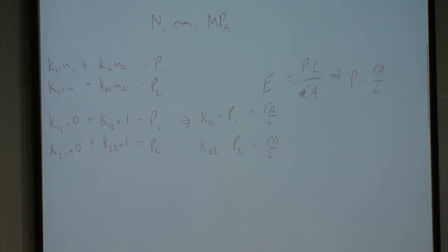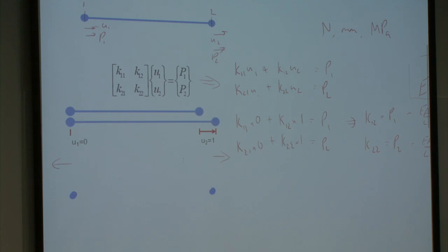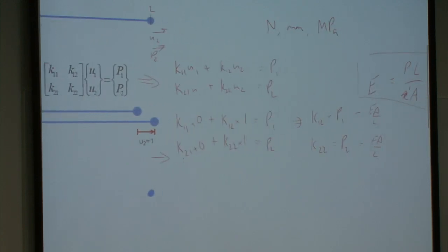Except that this equation here, which we've dragged from our first year mechanics knowledge, implies that you know the direction of the force. In fact, to extend it out, one of your forces is going that way and the other force is going that way, which isn't accounted for in our current maths. So K22 is positive EA on L, and K12 actually needs to be a negative.